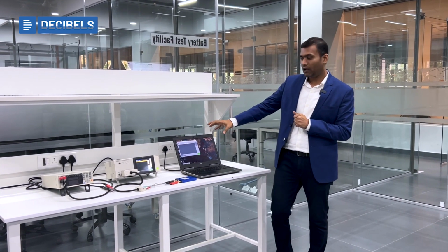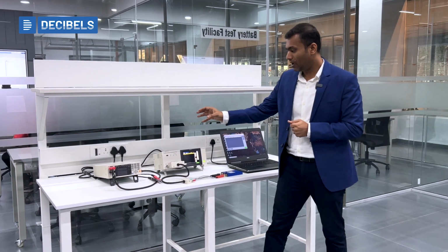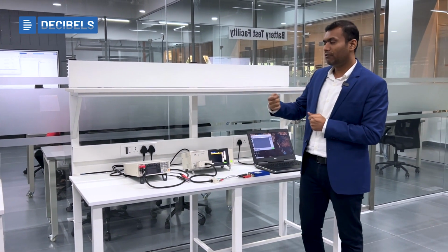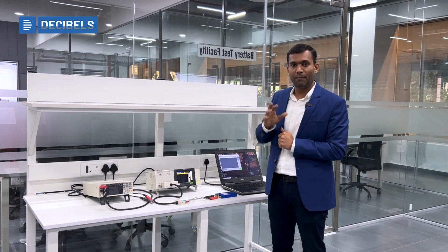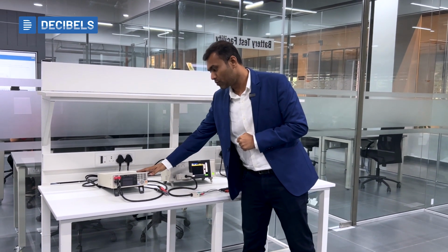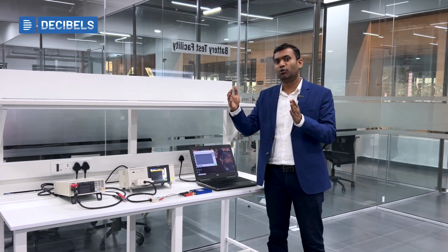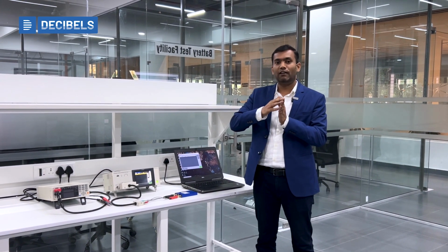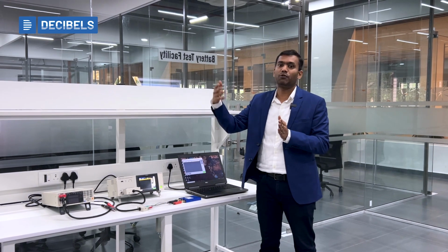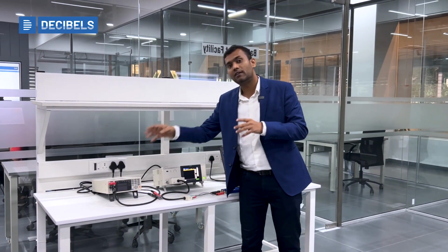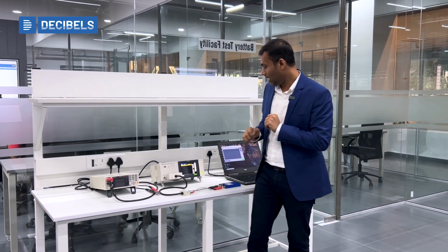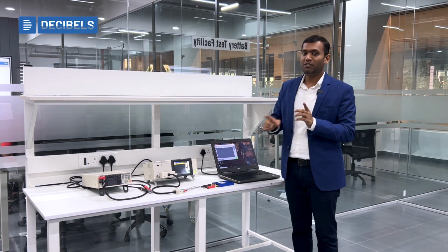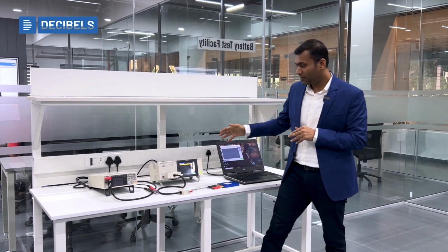We also have machines for the cell level, and machines for the pack level as well. At the pack level, we typically perform the test at 50% SOC and about 1 kilohertz. That is the standard we have been following in the industry. These machines come with different voltage ranges, because the cell voltage is usually below 5 volts, but the pack voltage can be 50 volts, 100 volts, 200 volts, 500 volts, even 1000 volts. The machine we have here takes 0 to 100 volts, but at only one frequency, 1 kilohertz. Here, this can go to a complete frequency band, but only up to 5 volts.